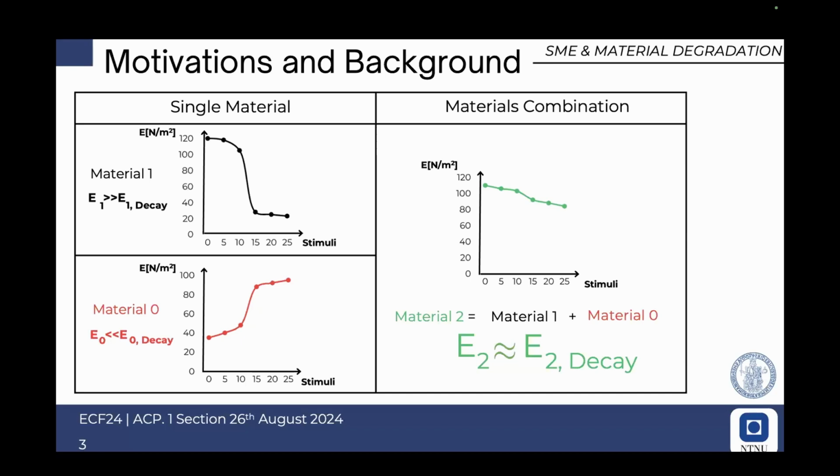So we created a new topology, let's say a new material, the BCO combination, that was constituted by a topological combination of two unit cells plus also a combination of two different materials. And we wanted to analyze how the mechanical property of this BCO structure changes depending on the stiffness ratio.